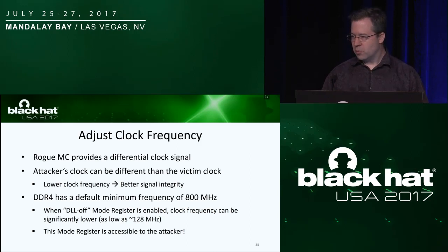Those mode registers, again, there's no protection on that. Anybody can read and write the mode registers. And as long as we set it back to the value that we found it in when we're done, the host system won't know that we are on there using a different clock and different register settings.